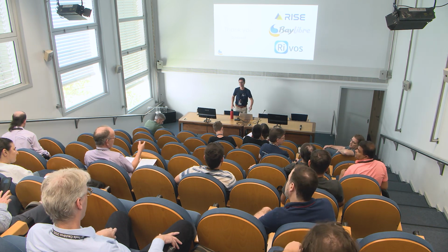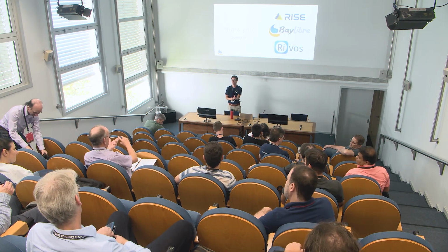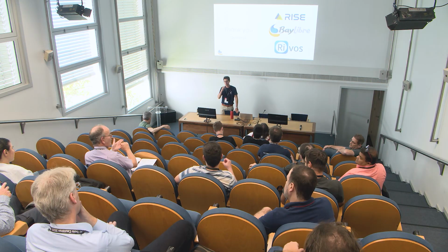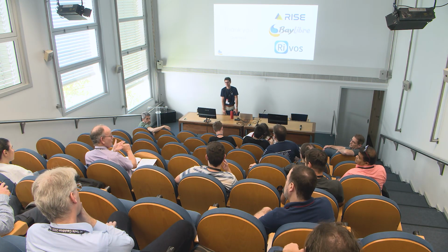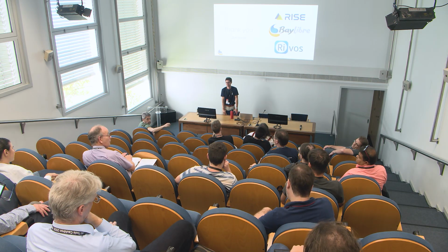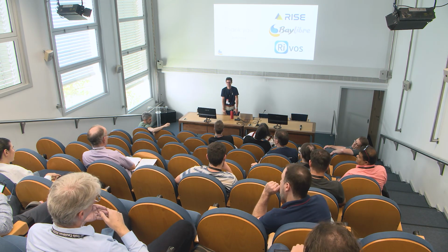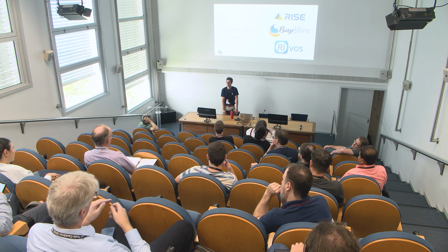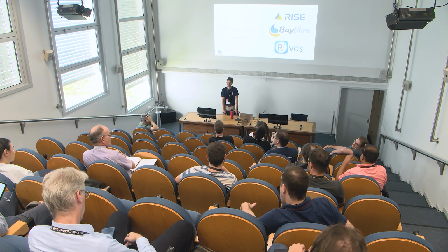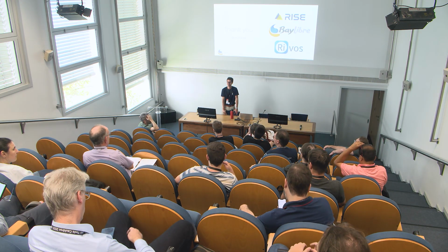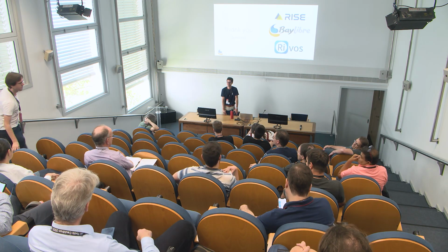Yeah, but the one thing that comes out, two things. One is, you're right, focus on memset and memcpy, because they dominate. Okay, get those off. But secondly, the microarchitecture for the vector is absolutely critical. That matters more. You can have vector copies that are massively parallel and just take a single cycle or whatever, and you can have vector copies where your VL is big and your vector's big, and it takes dozens and dozens of cycles. And it's the same instruction, and you've got to know that in the microarchitecture. So a number of times I said, do your microarchitecture before you even try. There's no point in optimizing generically because it won't apply to your chip.